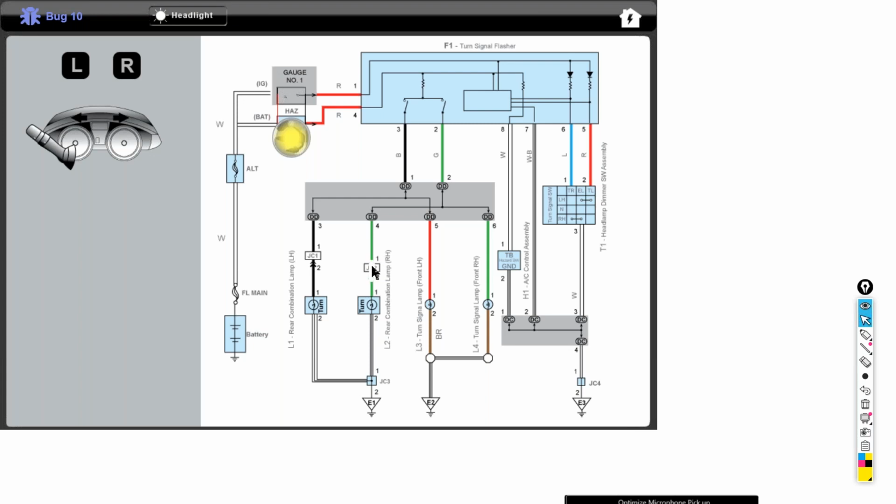Go to junction connector 2, unplug it. Stays on. Again, back here, goes out. So at this point, because when we disconnected here, it stayed on, that means it is between junction connector 2 and junction connector DD, and the green wire has a short to ground. Again, we have narrowed it down from multiple harnesses in the car to one single harness. Now it's just tracing the harness down, finding out where the short is, and repairing the wiring or replacing it, depending on how badly it's damaged.